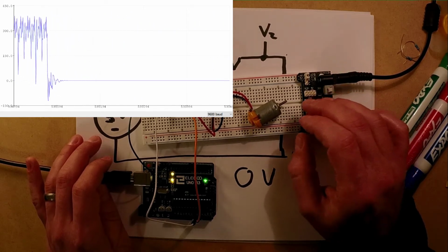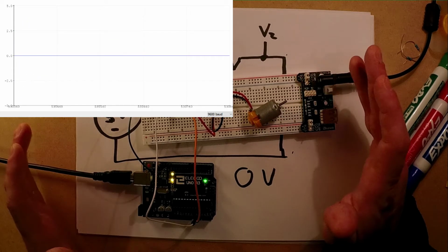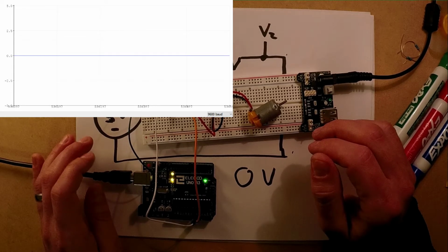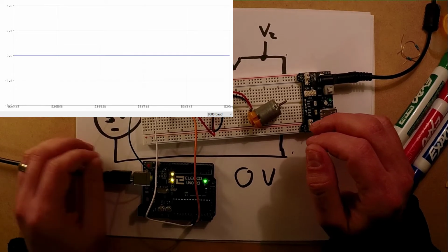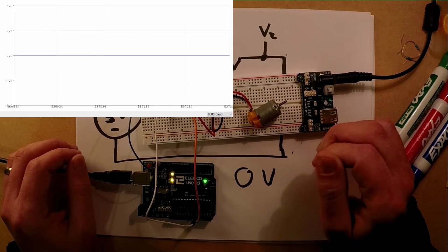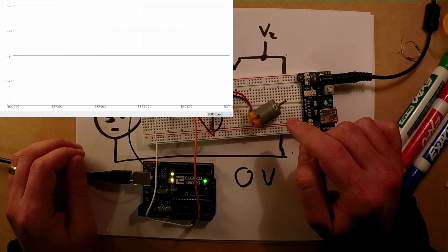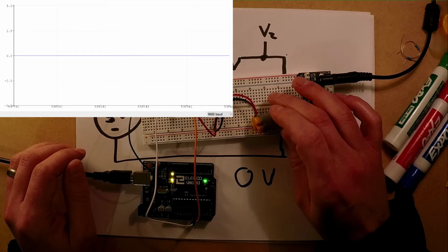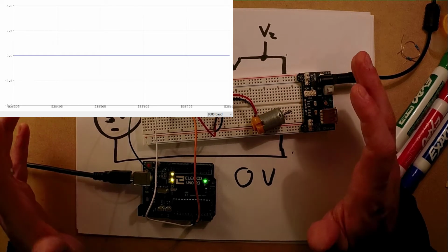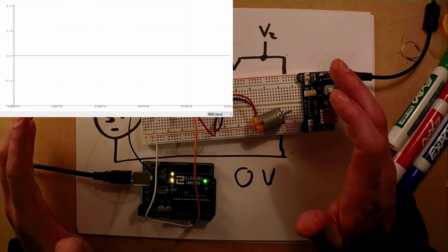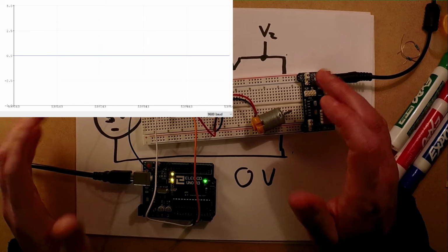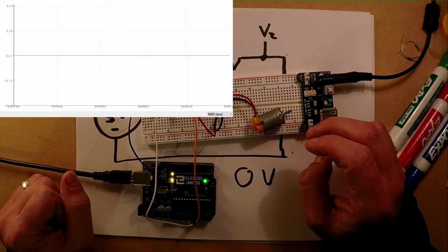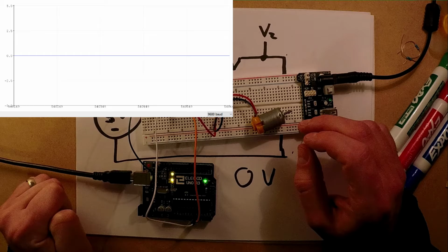All right, so that is the demo for today. This is really a pretty cool setup because you can measure the power of a small electrical load with just the items in your kit. This ends up being important because if you start to get to bigger motors, we'll start to need to think more about our supply. So hopefully what you realize from P equals IV is that you can't just pick a voltage supply based off its voltage alone. You need to consider how much power that voltage supply needs to deliver to the load, which means how much current it can also supply.